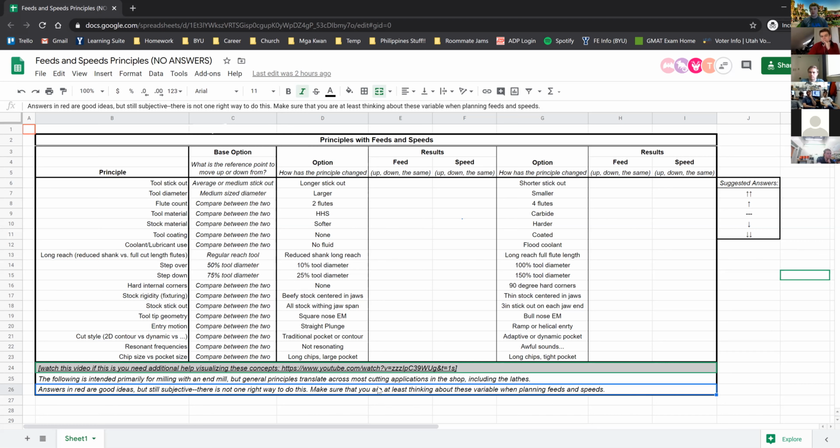That's what happens. We're going to be lucky enough with the Shop Saber that we'll have a vacuum table. But when you don't have a vacuum table, another consideration is your hold down method. I have a plate and I've screwed it down in 4 corners. That means the middle is liable to pop up and down and chatter vertically. So then things like a spiral flute end mill, which pulls up on material, is a bad idea.